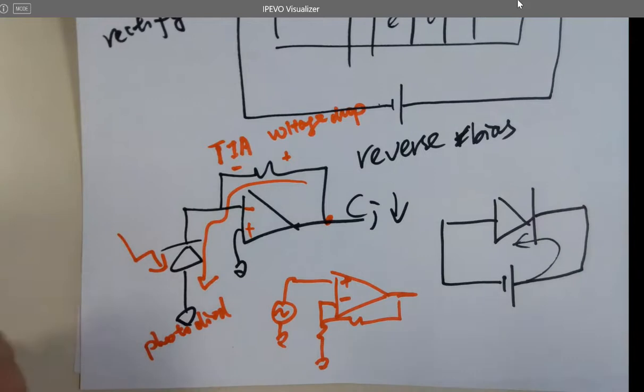So for example, the PMTs, it's a photosensor. I haven't used it before, but it is a photosensor. Some of the PMTs output current signals, and you have to connect the TIA to it, convert it to voltage. And some of the PMTs directly output voltages because they nicely already put a TIA in there. So directly, get a voltage. Why we always want to convert all the signal to voltage?